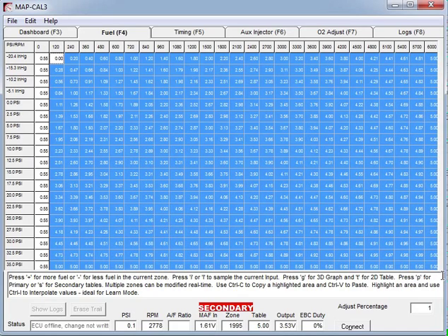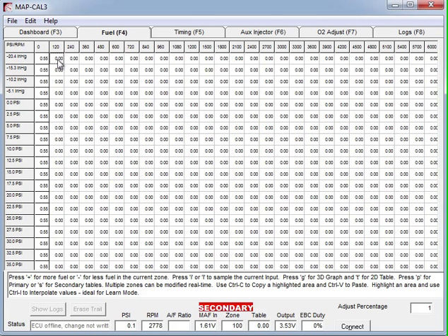So for example, if you've zeroed the fuel table, if you've got 1 volt here, and you know that this value is 1.5, but you're missing the bits in between, you just highlight those, press Ctrl I, and it'll interpolate the values in between. And this can be done any way. So for example, if you've just got some sections missing, this is 2 volts here, select those, Control I, interpolate that way. So that's the basic fuel tuning set up in table mode.